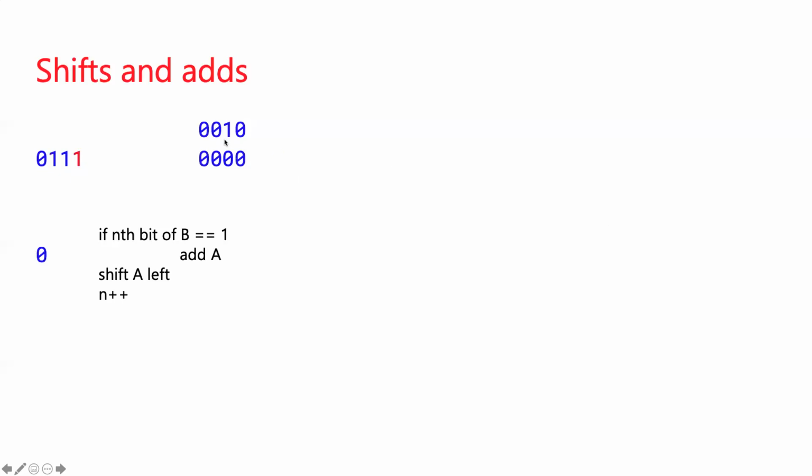We've got another example. We'll go through this real fast, or we'll try to, because it's the same algorithm. We've just changed the numbers. So now B is 111, so that's 7 in binary. And A, we're pretending, is just 0010 or 2 in binary. Same thing as before. So this is A. There's a 1 in the low order bit of B. So we add a copy of A into our product. So C looks like that.